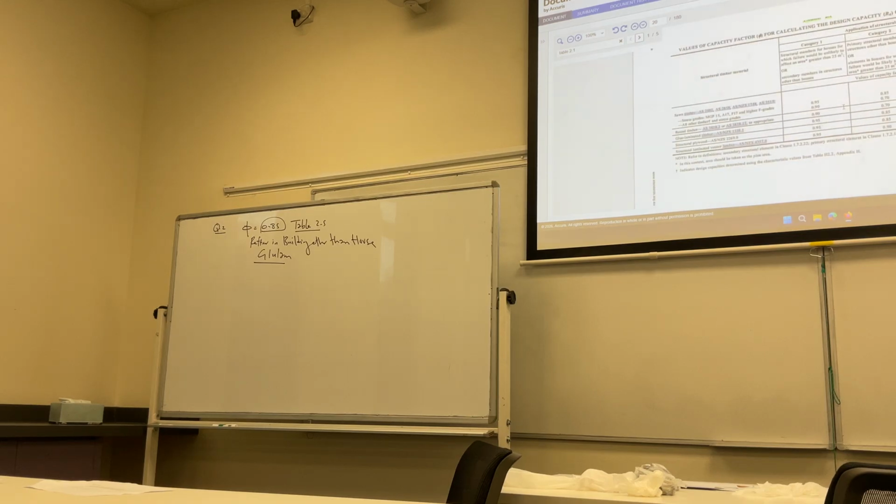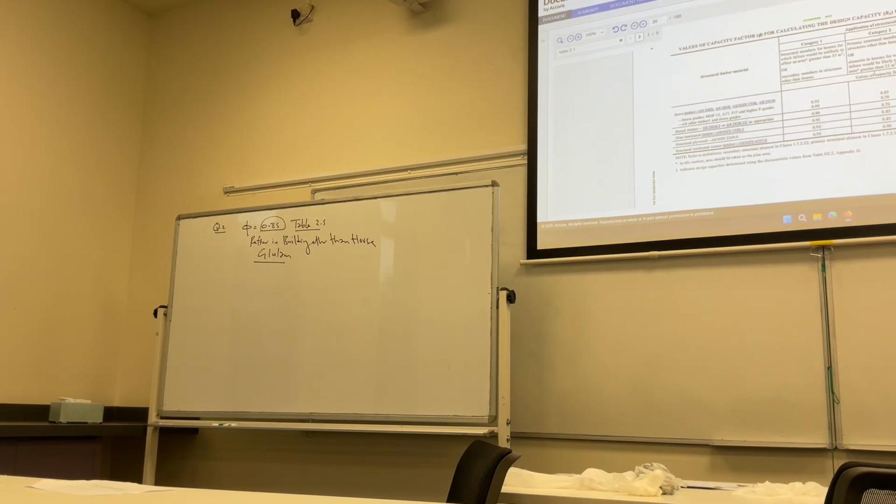Okay, so what is our case? Primary structural member in a structure other than houses. So I have category 2, not category 1. What is the grade of the timber? Glue laminated, so how much is the factor? 0.85.